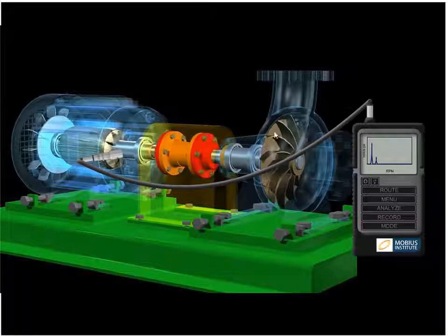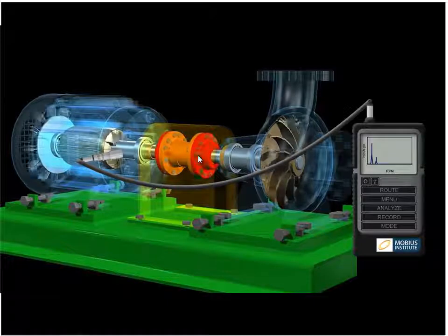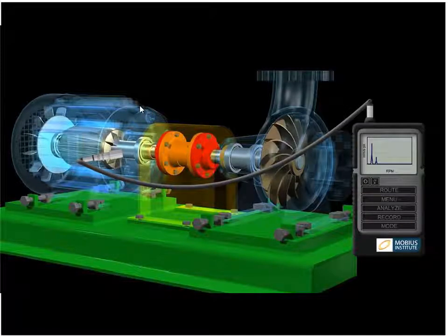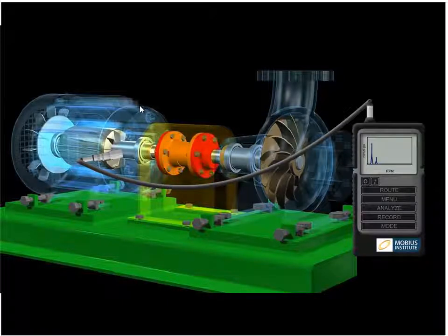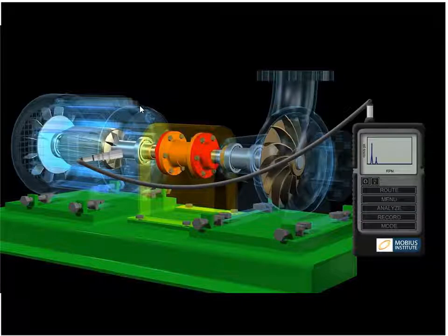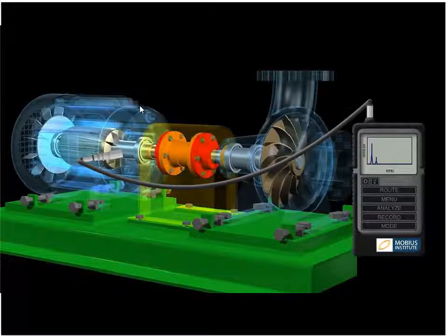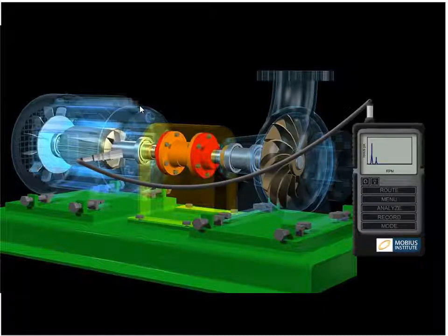So, for example, if it was rocking back and forward due to looseness or resonance, then the horizontal measurement will tell us about that. And whether it's vertical or horizontal, those two positions tell us about radial vibration radiating out. So if there was misalignment and offset or parallel misalignment, or unbalance, we get a lot of that sort of up and down and side to side motion. But with angular misalignment, for example, and certain types of bearing faults, it's more sensitive in the axial direction.